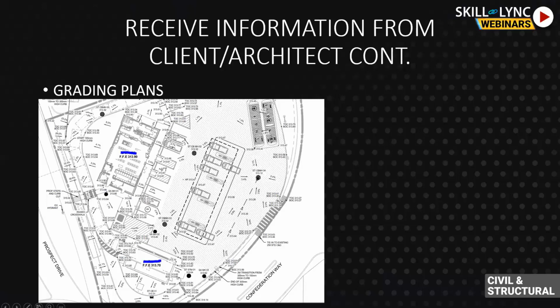So you have to look at the grading plan. And when you look at the grading plan, you get to know that there is a grade difference, a huge grade difference. So you would come to know that I have to cater for this in my drawings. I have to put some foundations which are deep enough to rest on some solid bearing strata. So that's where your grading plan also comes into the picture.